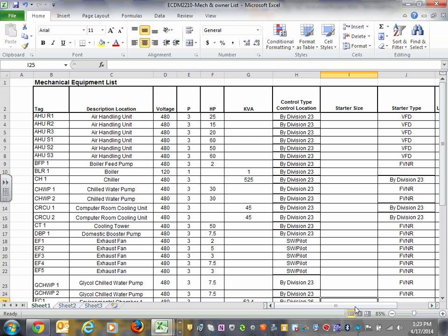What we have done, I worked on wastewater treatment plants at Short Hendrickson, and I remember going to the wastewater engineers and getting this information from them when you're sizing a service. They don't have it. So my boss and I developed a sheet that can size the building based on how many oxidation ditches you have and the size of the oxidation ditches, and how many clarifiers and the size of the clarifiers.